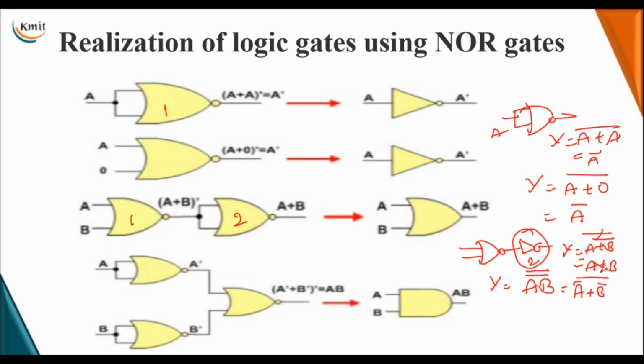So now we have made that expression completely into the form of the NOR function, but here we need to transfer the complemented inputs as the inputs to the NOR, so then it will implement the AND function. Hence, in order to complement the inputs, we use the first and second NOR gates, which will give the complement of A and B. Thereafter, you transfer those as the inputs of the third NOR gate.